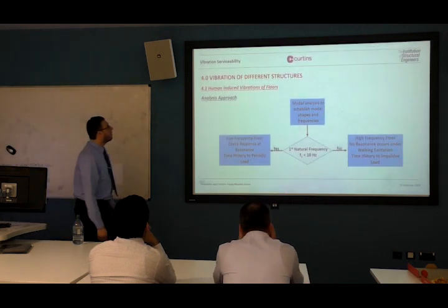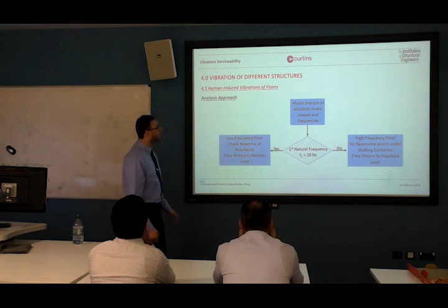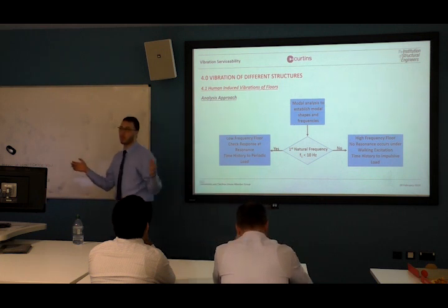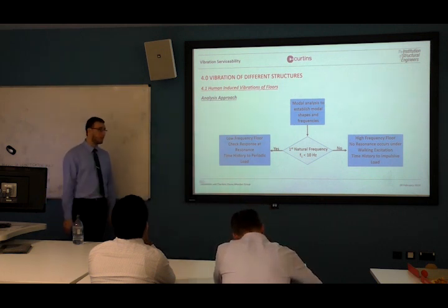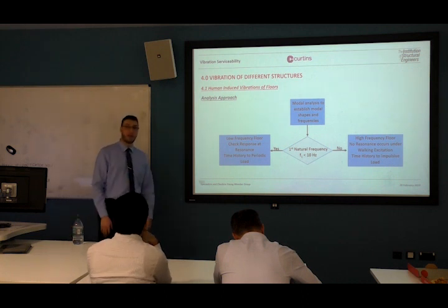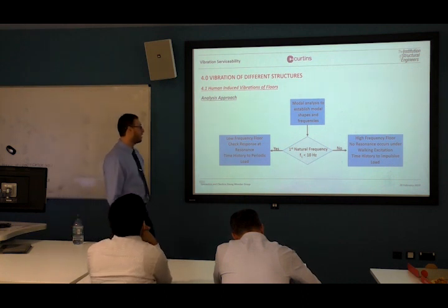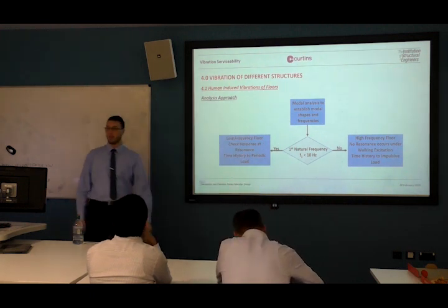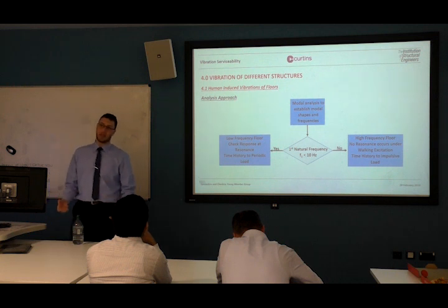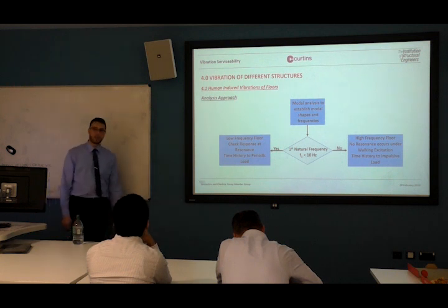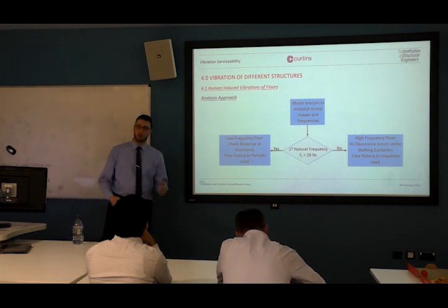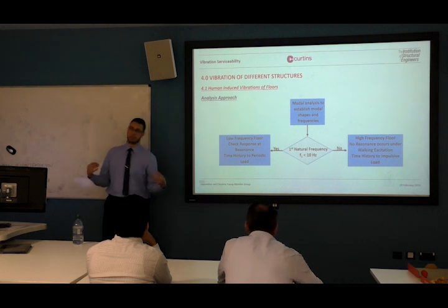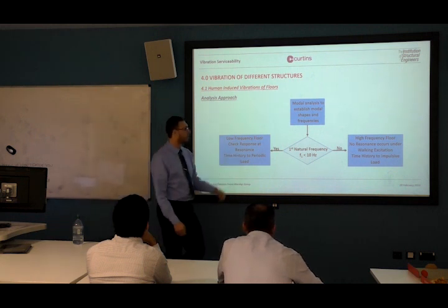So if I talk about what we do for floors, the approach is very simple actually. Start with modal analysis of the structure. Have your floor plate model in FE, and then do modal analysis, and then check the frequency. If your frequency is less than 10 Hz, then this is a low frequency floor, and probably if you're talking about 4 meters and more, and the design is quite economical, then you're going to get a low floor frequency.